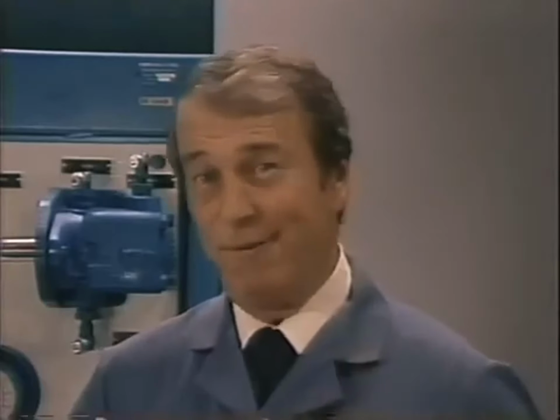Too often people think that a pump pumps pressure, and that's not only wrong, it's downright misleading. I say that because the pump gets blamed whenever you can't build up enough pressure, and that isn't even the pump's job. All the pump is supposed to do is make the oil flow. Pressure is caused by resistance to flow. If you don't have enough pressure to do the job, it's usually because the oil has found an easier way to get back to the reservoir. Next time someone has this problem, find out where the oil is going, and you'll be a hero.